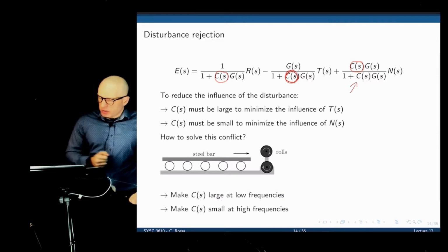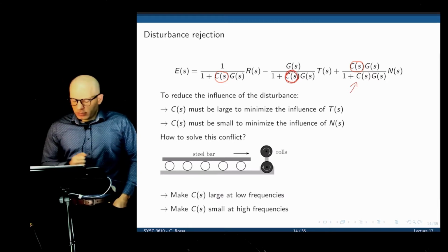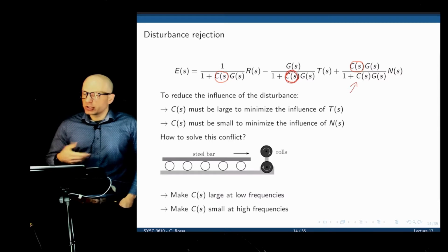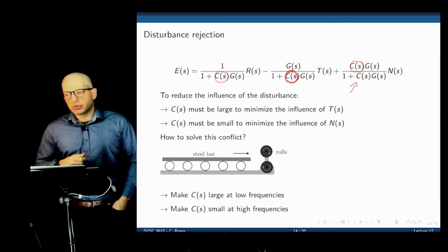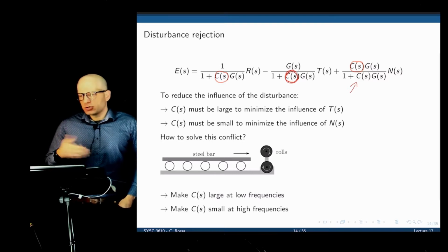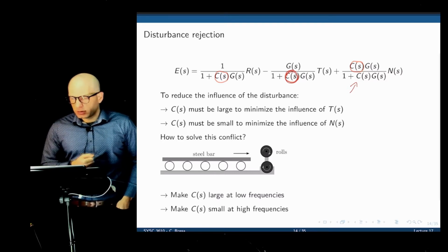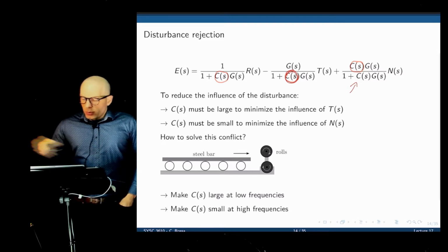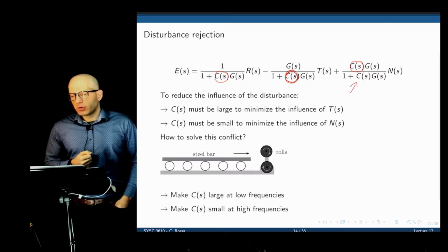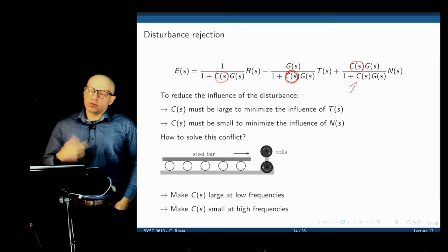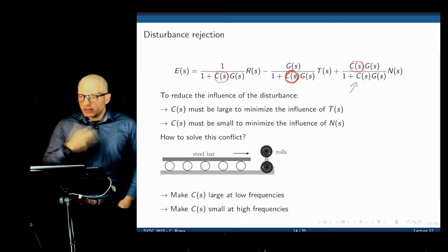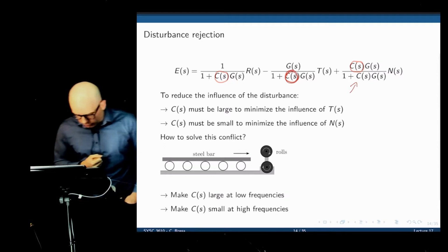Considering the mill that we had as an example in the beginning, let's say we are measuring the speed using a sensor. We are injecting noise into the system, and this noise could be in the order of kilohertz in frequency range. We have one steel bar coming at a second, for example, through the rolls, which means that the disturbance itself will only occur at 1 hertz. So we can say that this is actually an example that works for most systems.